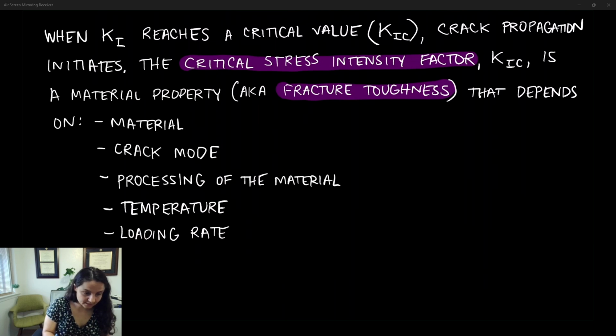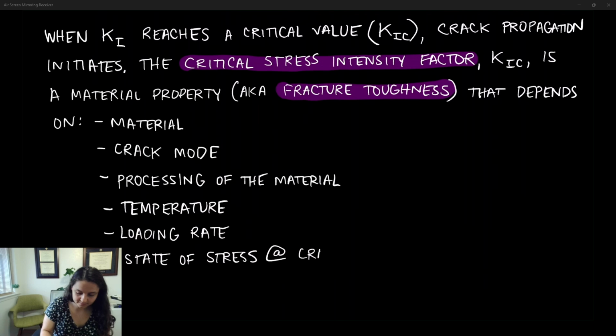And the state of stress at the crack site. So it does matter whether you have plane stress, plane strain, or a triaxial stress state, and it matters what the magnitude of those stresses in each dimension are.